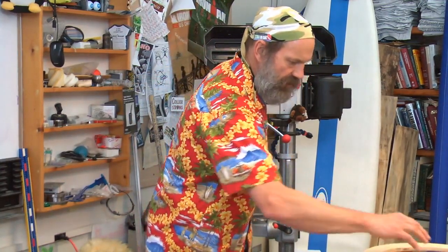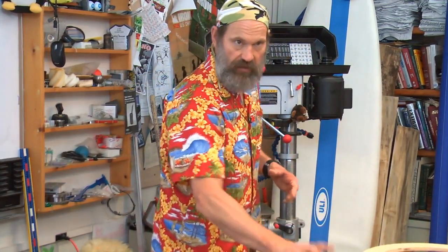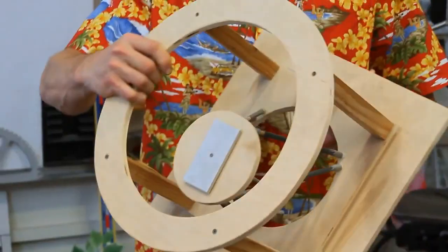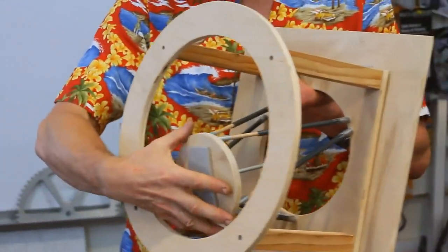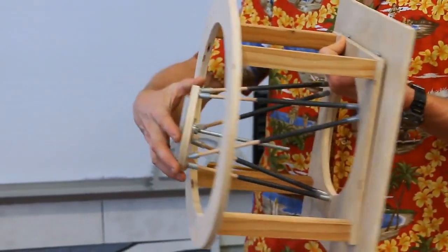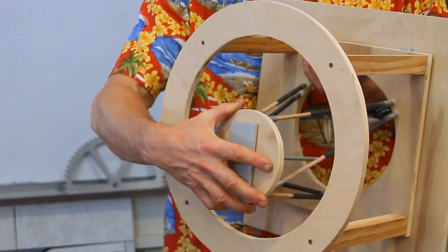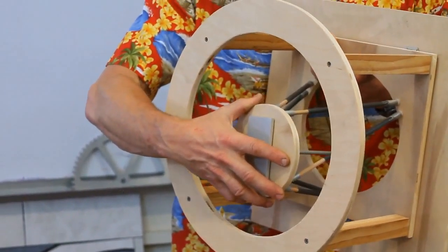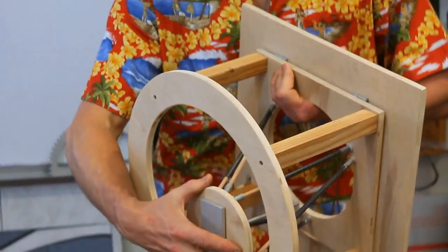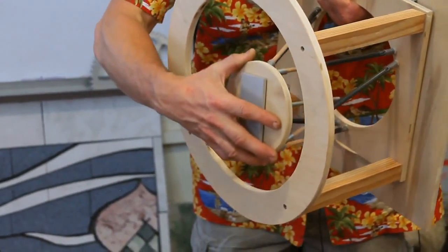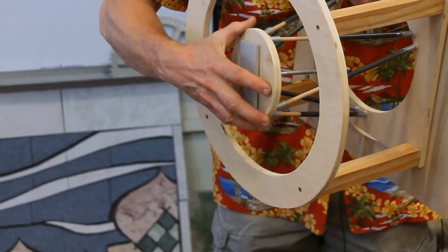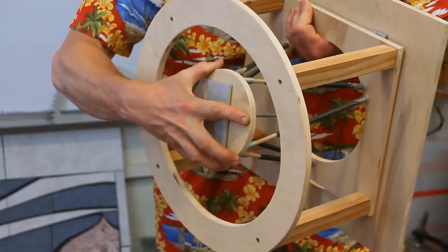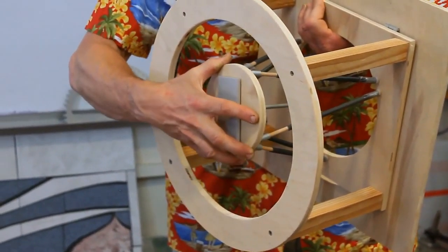And remember from last time we were looking at linkages, both linear and rotary. This is a very special type of linkage. It's called a hexapod. And a hexapod has 6 struts, hence hex. And this is the same kind of mechanism that's used in a flight simulator. And notice they form triangles. So if the legs of the triangles can extend, this thing can move all over the place. So I can move linearly, up and down, I can get rotation, I can tip. Now the motions, angles I can move are a little bit limited, but you can get all those motions at once.